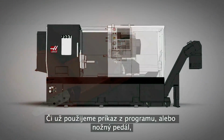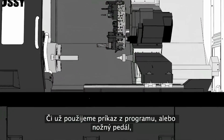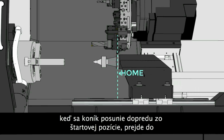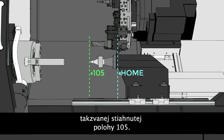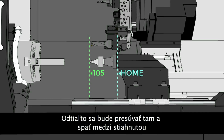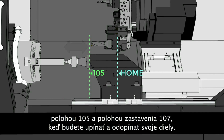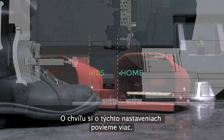Whether it's commanded from a program or by the foot pedal, when the tailstock moves forward from home position, it moves to what we call the retracted setting 105 position. From here, it will move back and forth between the 105 retracted position and the 107 hold position as you clamp and unclamp your parts. We'll talk more about these settings in a minute.